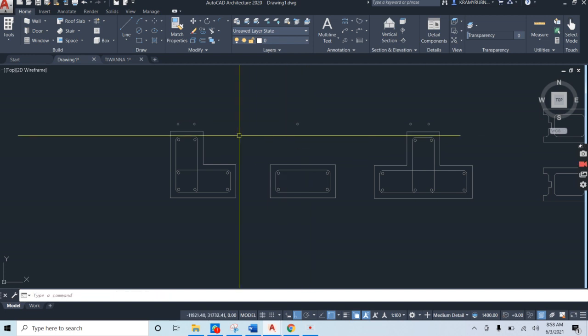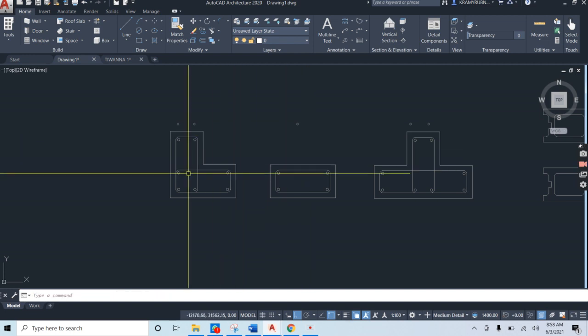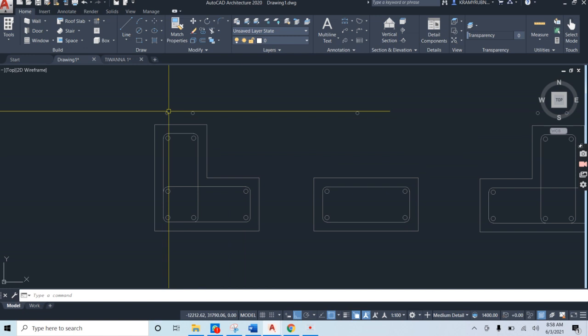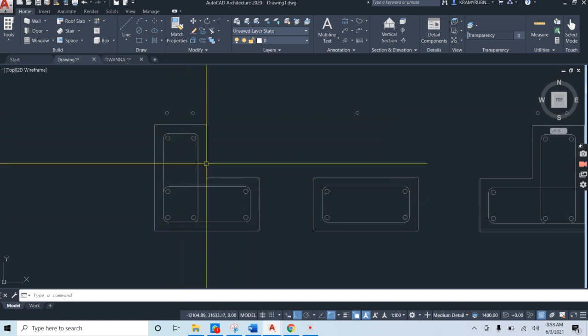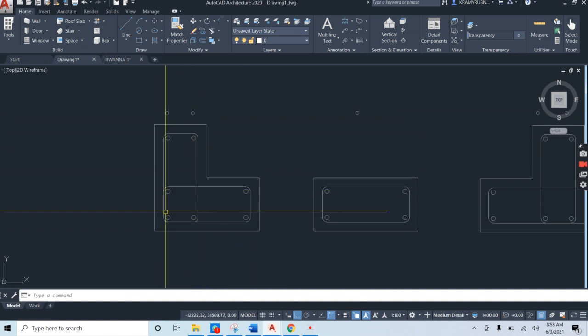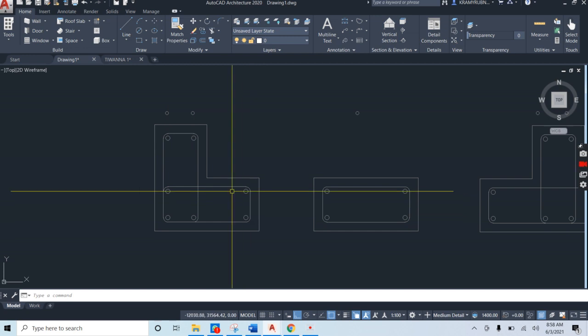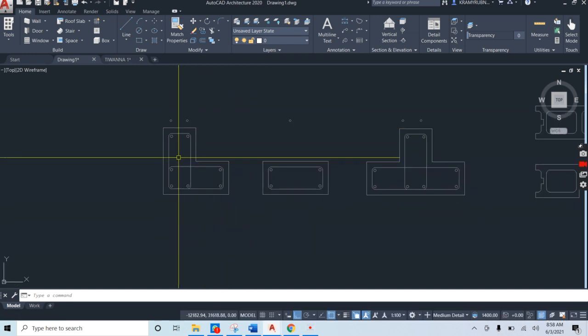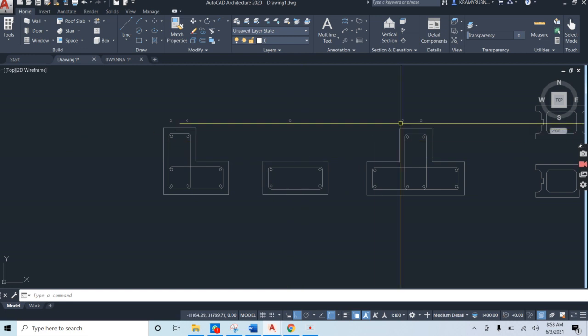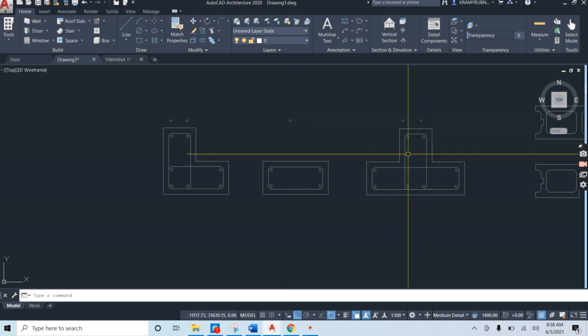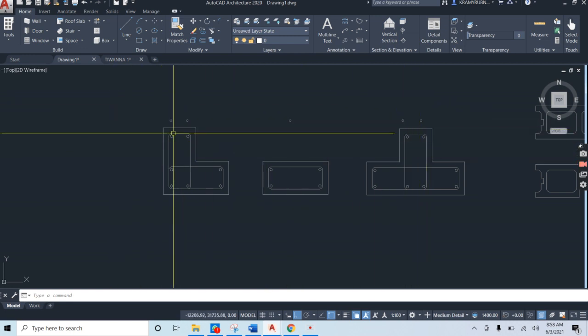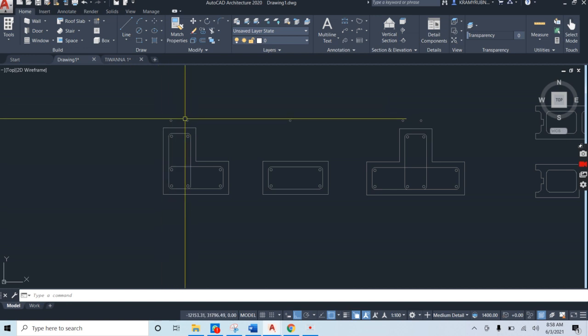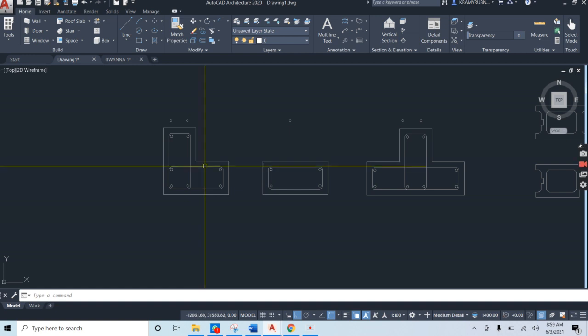Let's have 2 circles. We want those circles because we're going to be sweeping them onto our stirrups. And that's why we basically have 2 for this one, 1 for this one, and again 2 for this one. Because once you sweep the circle, you would have lost the circle, and so you would have needed another circle for our other stirrup.